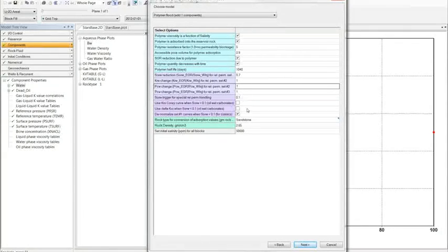Now you notice down here that there's also some special options for special well perm handling. This is typically used for one case when it's an oil wet carbonate. The SORW may be quite low because the SORW may have come from centrifuge data, giving you a very high capillary number, very low SOR.